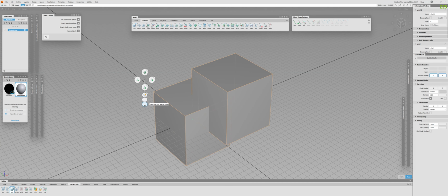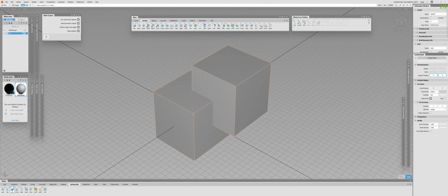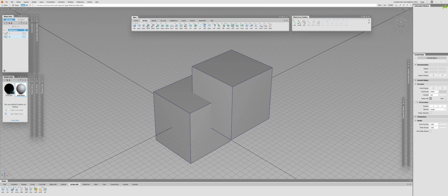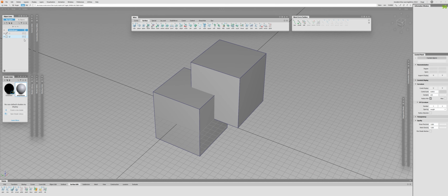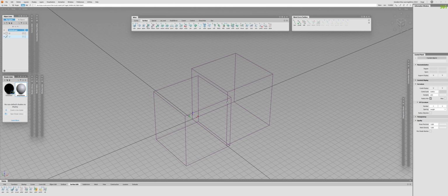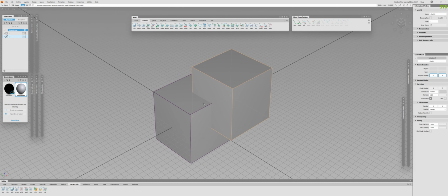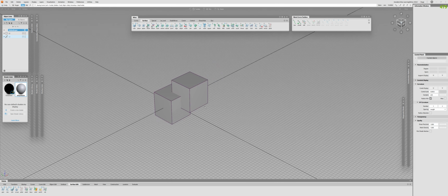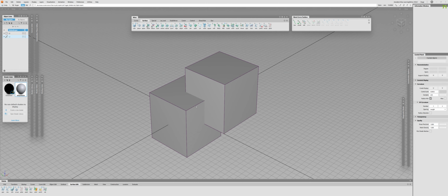So now let me create a new layer from them and hide it. And these ones, let me create a new layer from them as well. So basically now these ones are the original surfaces, and these ones are the stitched version. As you can see, they have a different color. Now, it's important to note that I can't actually perform anything with them except moving them around and performing the Boolean operation, and that's it. I can't select the specific surfaces, I can't turn on my CV controls, nothing like that. But that's not a big issue, because we can stitch and we can unstitch it back. But before we do it, let's perform the Boolean operation.